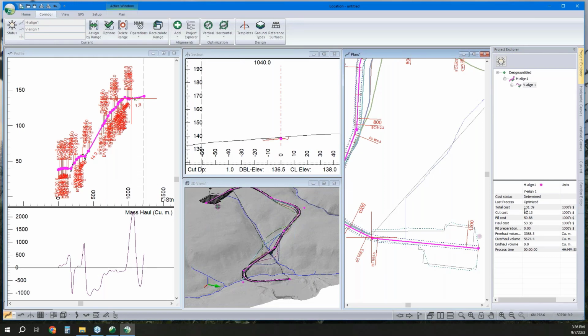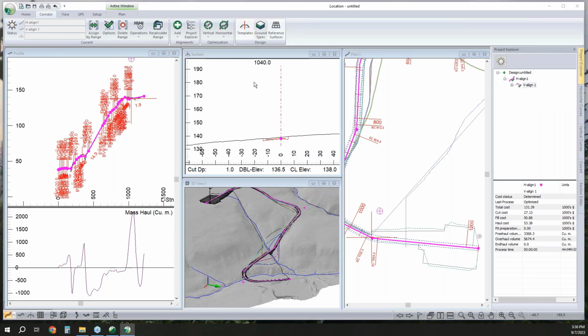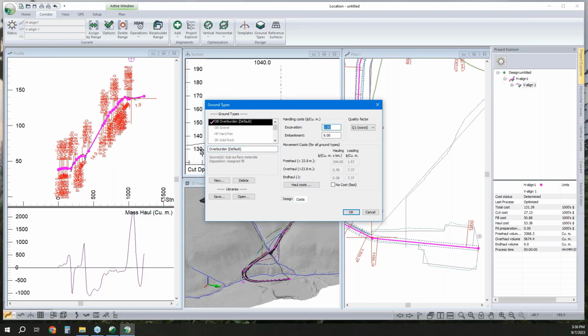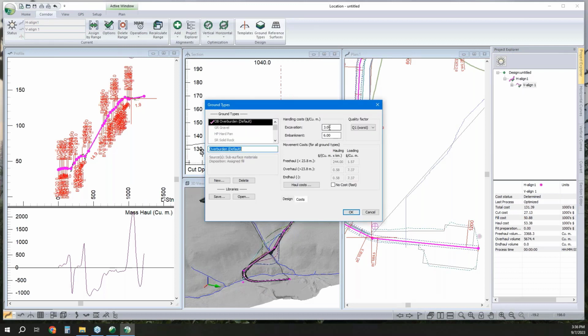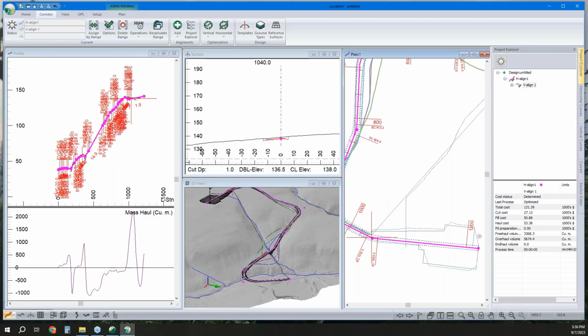According to the unit costs that we've put in there, our earthworks are at $131,000. Keep in mind if those numbers seem out of whack to you, it's a product of my geometry and the site. And more importantly, if you're paying different unit rates, you can change that and the cost will scale. The nice thing about this is, in order to get a reasonable vertical, your costs don't have to be exact. It's going to want to minimize cuts and fills and minimize the distance that it gets moved.